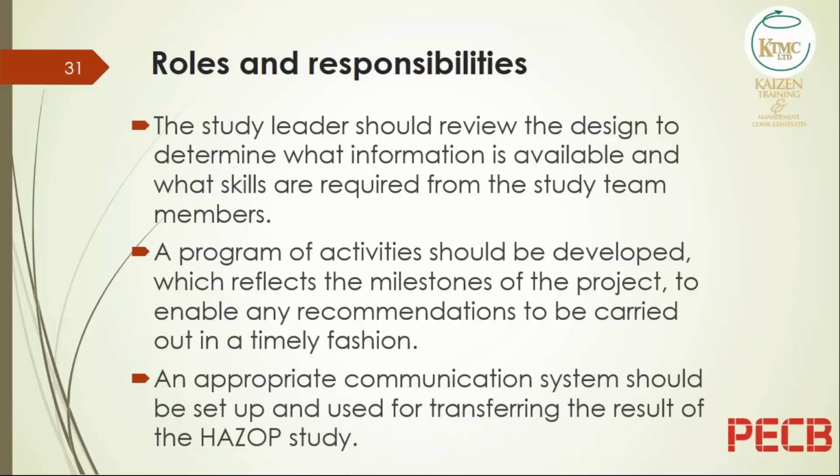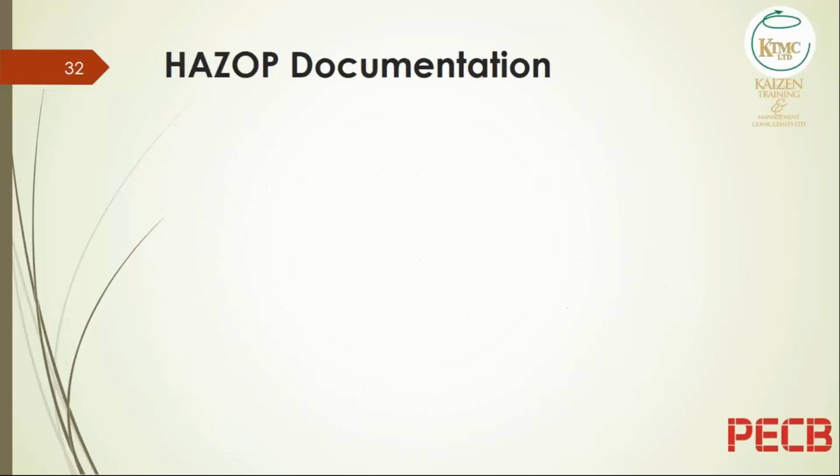An appropriate communication system should be set up and used for transferring the results of the HAZOP study. And this is important. So is it going to be by email? Is it going to be face-to-face communication? How is it going to be done? This must be agreed beforehand.